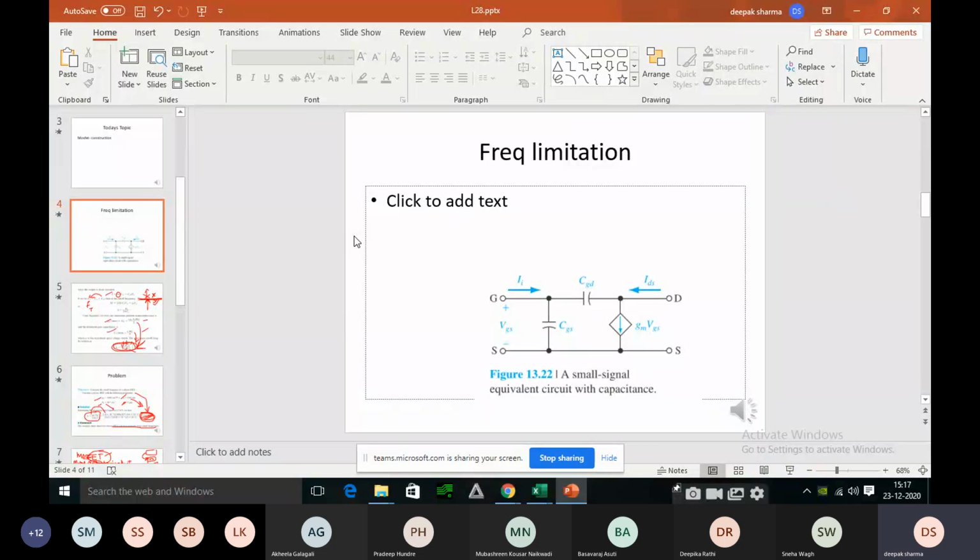What do you mean by transition? The movement, right? The charge carriers require some amount of time to move from one point to the other, say from source to drain. Electrons move from source to drain in a JFET, so it requires some time, right? That time will be considered for frequency limitation.